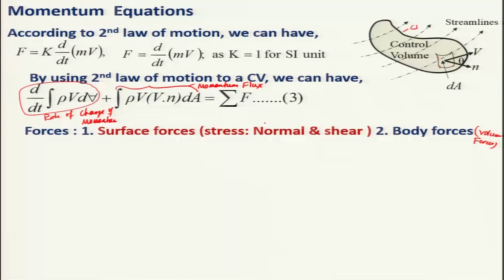and this stress will be acting normal to the surface of this control volume, and that is basically the pressure. And shear will be acting on the surface, along the surface, whereas the normal force will be acting normal to the surface. These forces acting on the control volume will make the momentum move across the control volume, and of course there will be accumulation, a rate of change of momentum, in the control volume, and that is known as the momentum conservation equation.